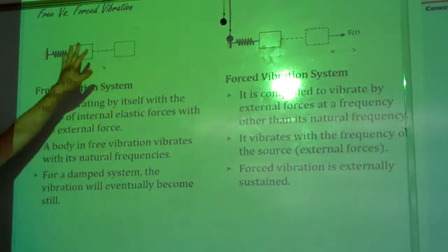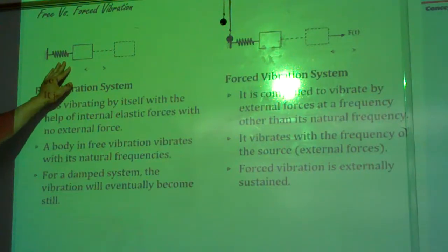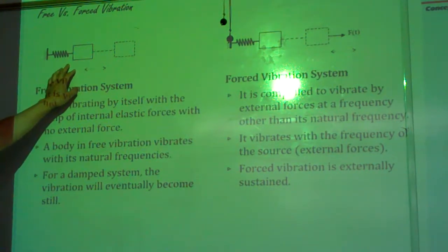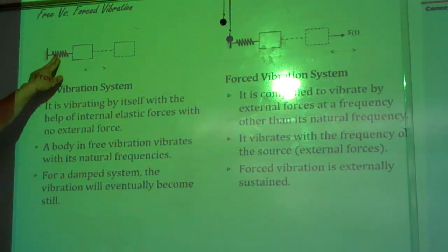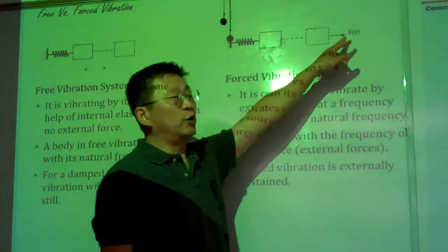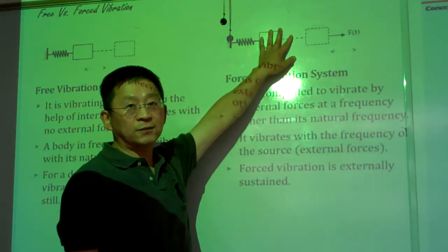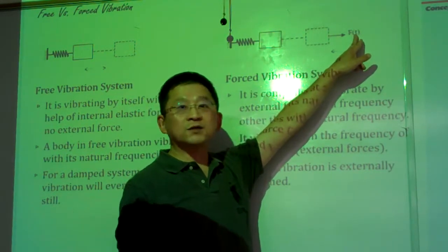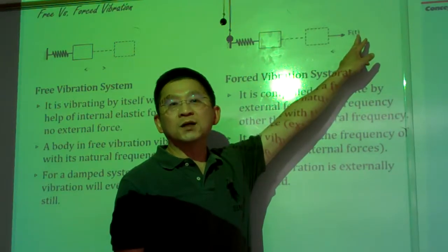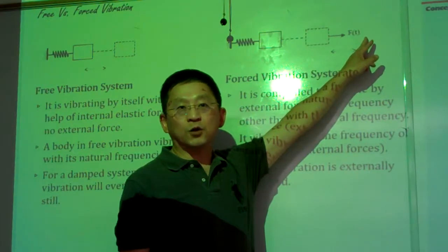In terms of free vibrations, we're only going to find the features of the vibrating system, for example, the natural frequencies. The natural frequencies are the intrinsic features of the system once the spring and mass are determined. For forced vibrations, in addition to the natural frequencies of the system itself, we also deal with the working frequency, which is the frequency applied through the loading.